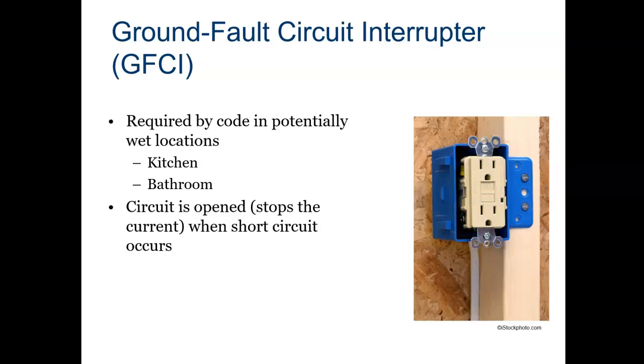It should be noted that you may not have a receptacle like this in your bathroom or right next to your sink. In North Carolina, you are allowed to have a remotely located GFI. In my house personally, two of these are in the basement, so if you pop one off in the bathroom, you have to go all the way down to the basement and press the little reset button in it.